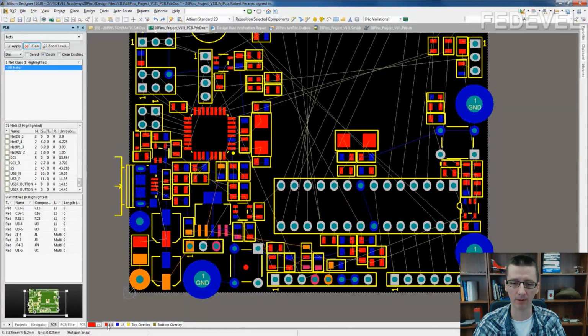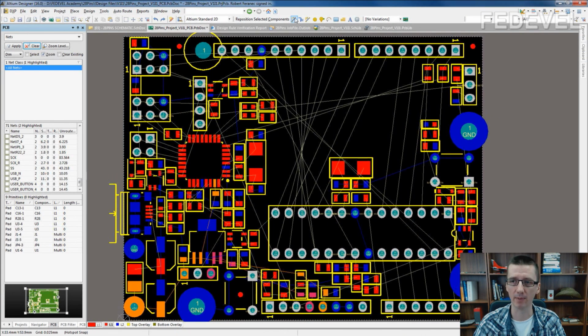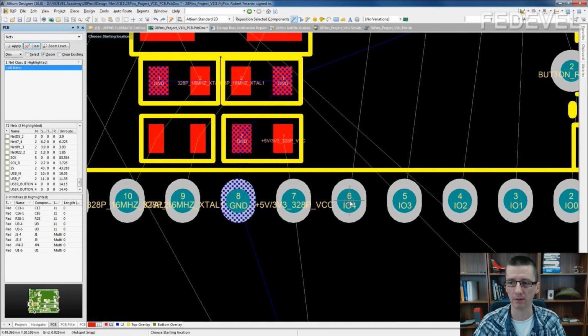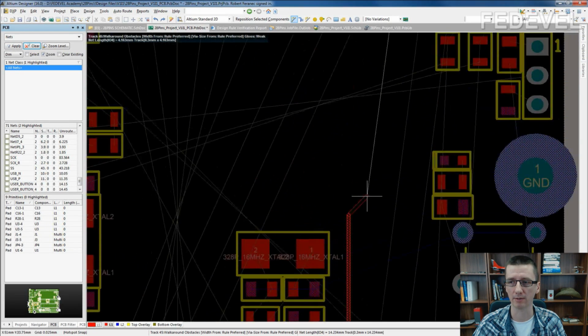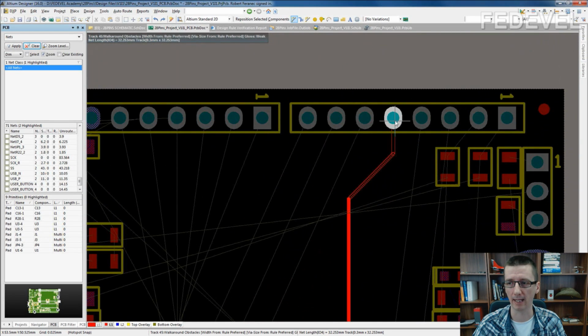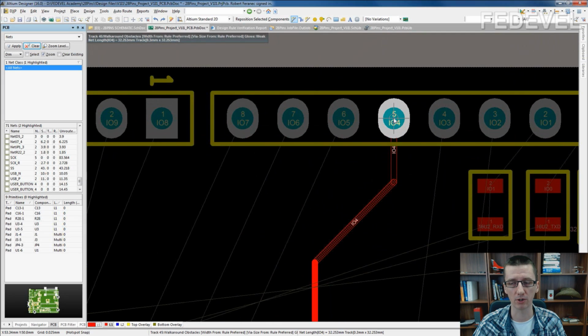Click on the layer 1, that's the layer where we would like to draw the tracks, and click on this button here. This is what is going to draw the tracks. Click in the middle of a path. You see the special cursor, and just drag the track. When you would like to finish it, double click with the left button on your mouse and then right click once. 1, 2, 3. Okay?